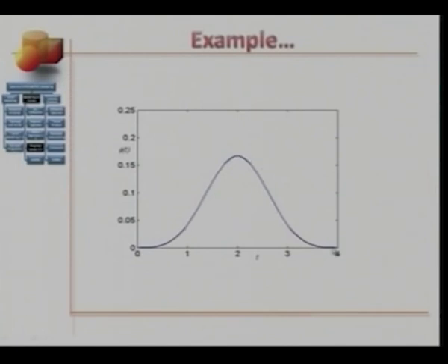Recall that we had used a few conditions. The position, slope, and second derivative at this point is 0. The position, slope, and the second derivative at this point are 0. And this B-spline basis function is non-zero over this knot span. This knot span has 1, 2, 3, 4, 5 knots. Also recall that we had called this basis function a fundamental spline because the 4 knot spans were essential to provide the minimum support for this basis function.